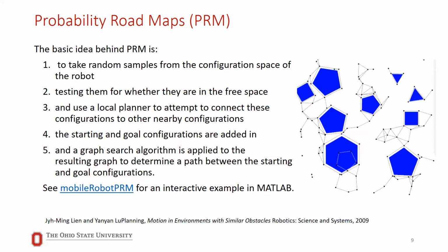In this method, you define the free configuration space, where the robot can actually move, sample points, and then create local trees from the point where you were. All the sampling points start creating trees and finding their closest neighbors, and these little branches connect to each other and create the tree.